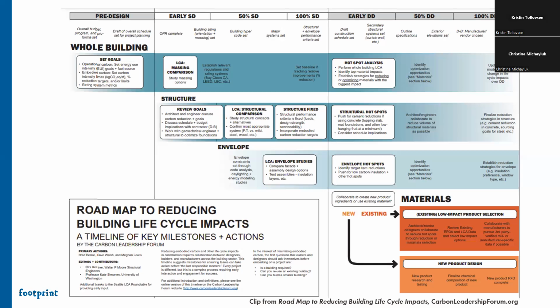And if you're going through near the end of construction, you can have some real information on those specific quantities that are involved. So there is always an opportunity to discuss life cycle assessment, but the sooner the better so that changes can be made. It ends up being really challenging to make changes to a concrete specification if the issued for construction set has already been done. So trying to get those changes and questions in and those investigations as early as possible is always appreciated by everybody on the team.